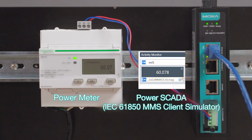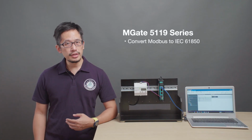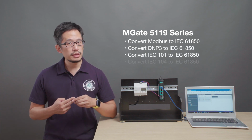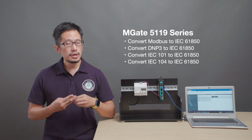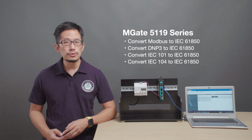Over in our power SCADA, we can now monitor the frequency data coming from our power meter. In addition to Modbus, the MGate 5119 series can also convert DNP3, IEC 101, and IEC 104 protocols, so you can easily connect your legacy power devices to your IEC 61850 power SCADA.